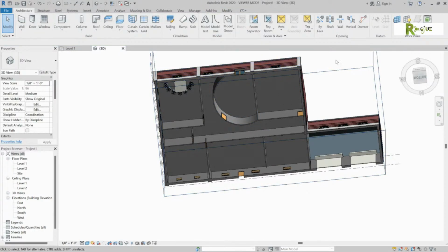Over on the properties of the view, this is your view's properties. You see, this is also another place to change the scale. If you scroll down a little bit, you're going to see one that says Section. Nope, not the browser. That one, yep. And that's why you went past it. That's got the section box in there.